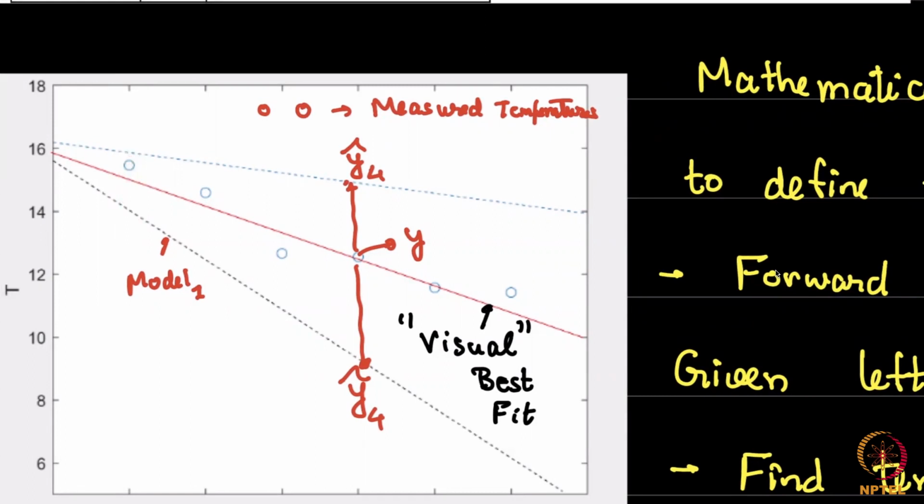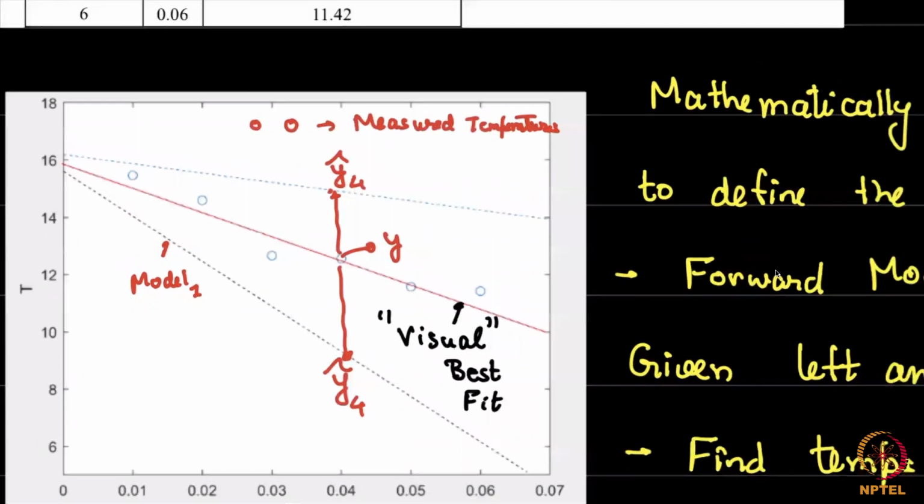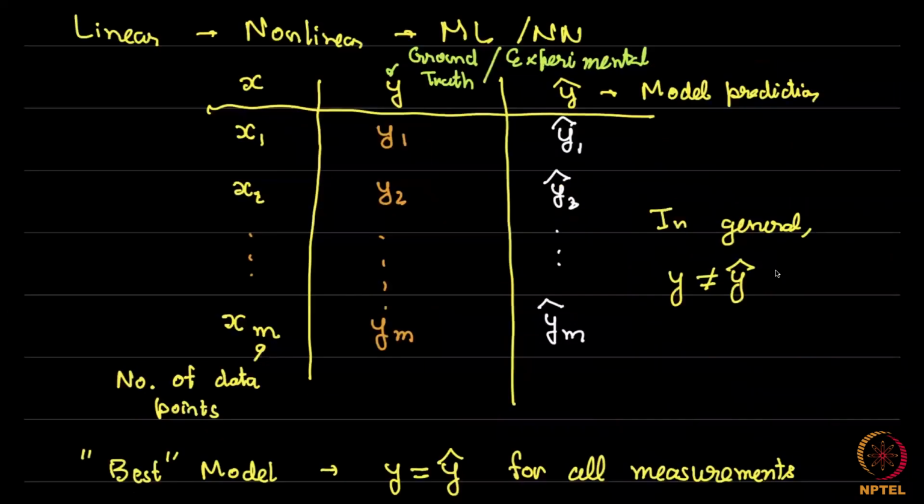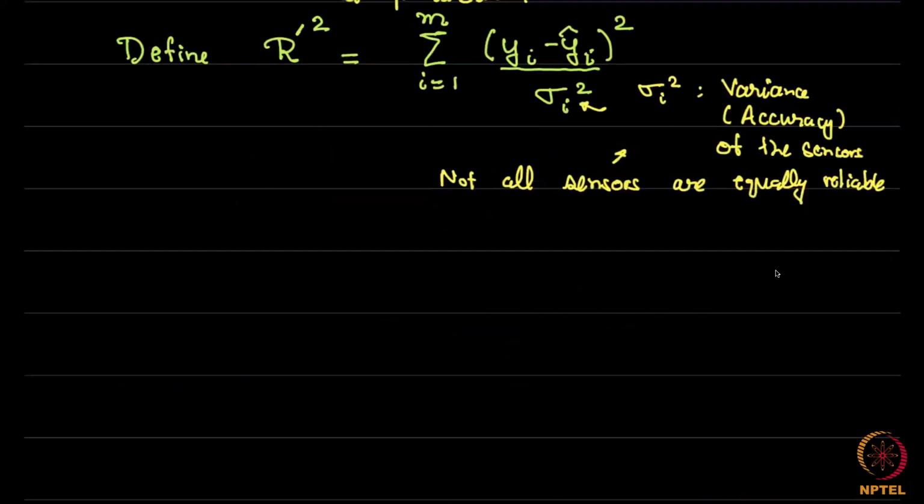Whereas a big gap in a measurement device which is less accurate doesn't have to be given so much emphasis, because this sensor has always given a lot of error. So maybe the fact that the model and the truth are very different need not be given so much emphasis. So what the sigma does is gives different emphasis to different sensors.